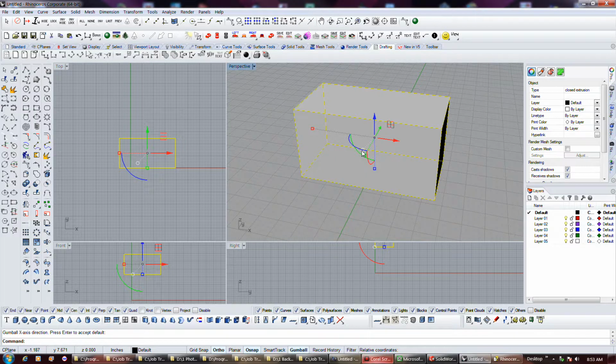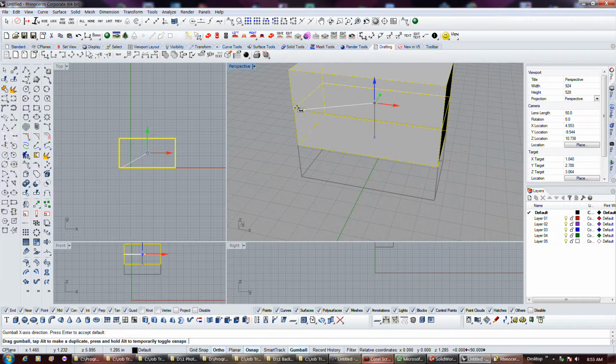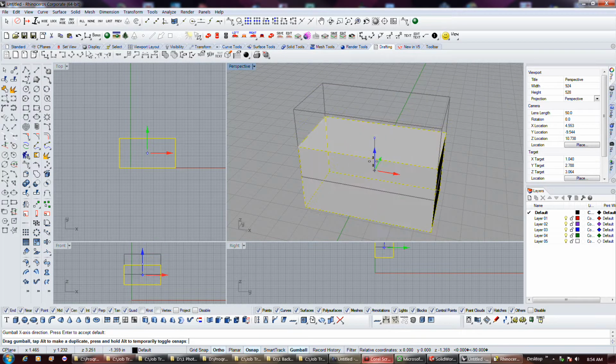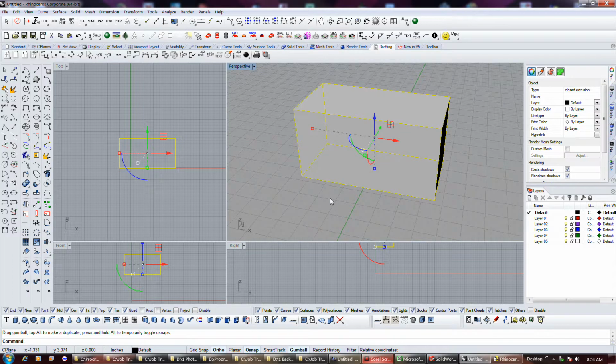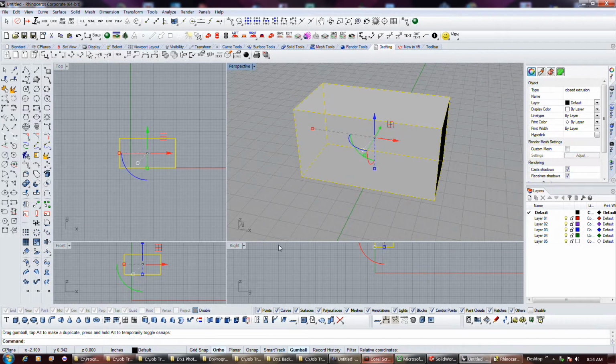Now of course in Rhino, like I said, we've got all these snaps turned on here. And by the way, if you're in the process of doing something, I'm holding my left mouse button, but if I right-click, it'll release it and won't modify it. I think some other programs do that. Again, if you wanted to disable the snaps, I could just disable them. If they get in your way, but again, pressing the Alt key is probably the best.